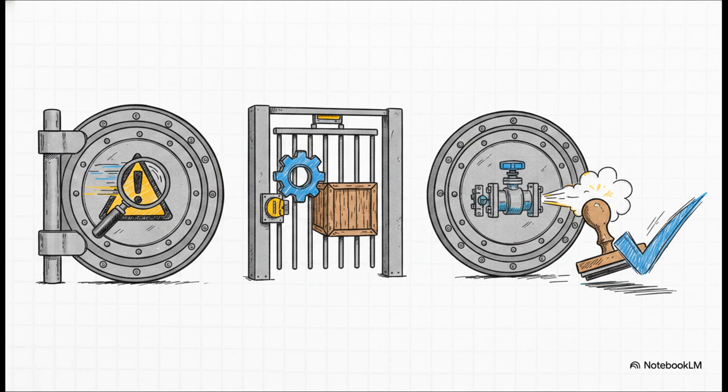To legitimately stamp a drawing IFC, 3 absolute conditions must be met. First, every single action generated from that HAZOP review must be completely closed out, no exceptions. Second, all finalized vendor data, meaning the exact footprints, weights, and nozzle orientations of purchased equipment, has to be incorporated into the model. And third, the PSV, the pressure safety valve sizing, must be absolutely confirmed. These aren't just guidelines, folks. These are mandatory binary gates.